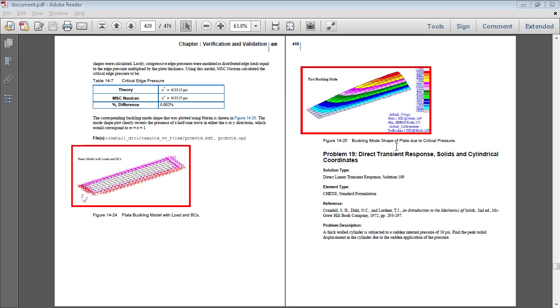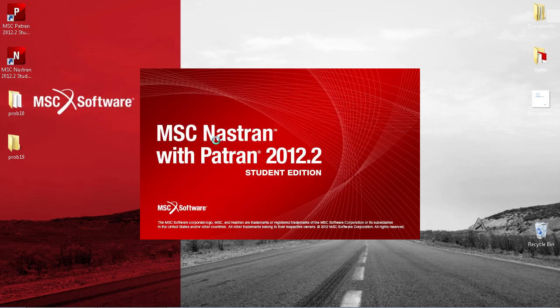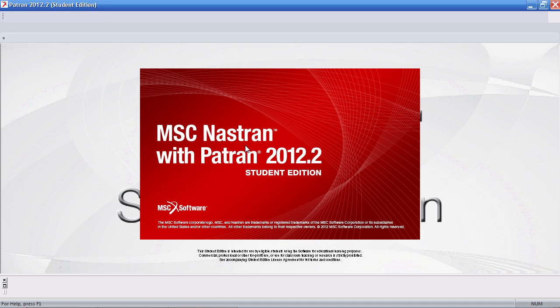In this video, I will be performing a direct transient response analysis using solid elements and cylindrical coordinates. Full details of this exercise are on page 410 of the PDF linked in the video description below. I'll first start a new Patran session. The units for this exercise are in inches, pounds, and psi.